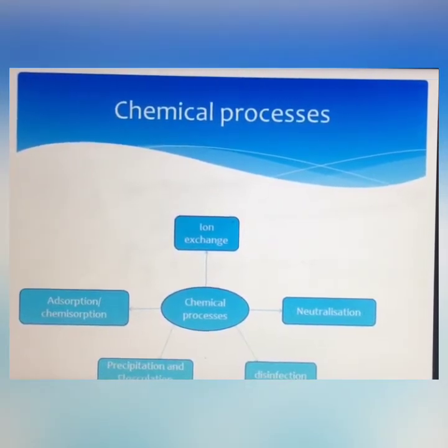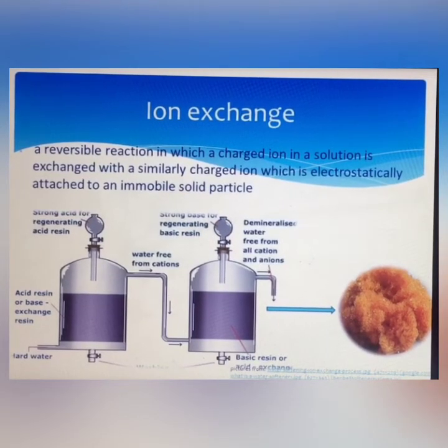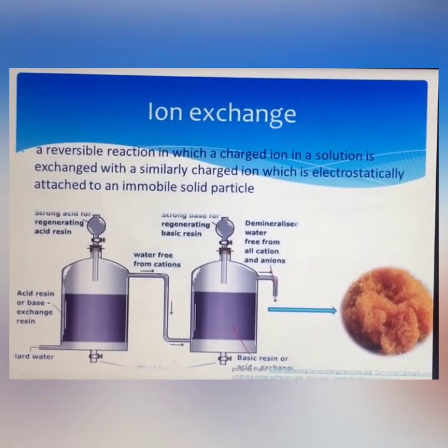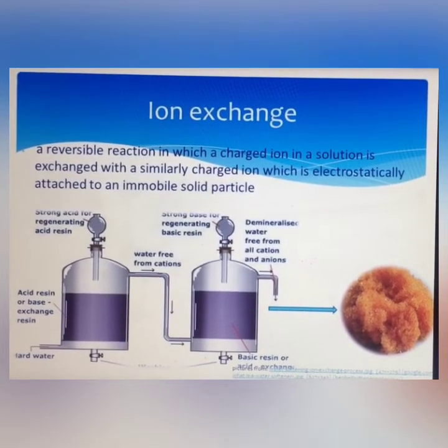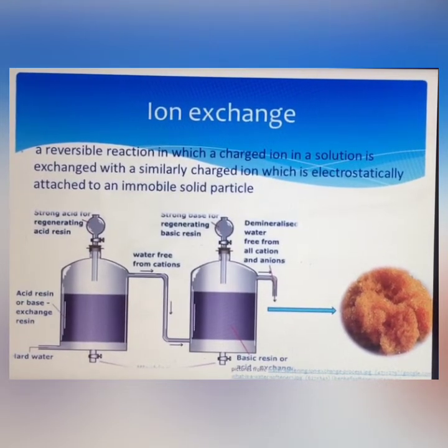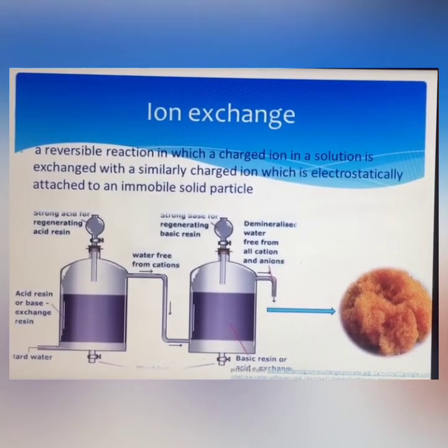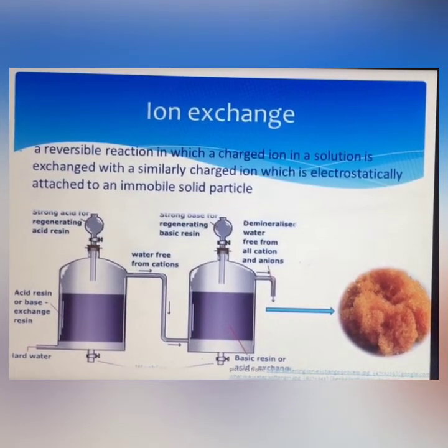These are the most important chemical processes used in wastewater treatment. Ion exchange. Ion exchange is a reversible reaction in which a charged ion, which is unwanted in the wastewater, is exchanged with a similarly charged ion, which is electrostatically attached to an immobile solid phase. The implementation of this method is for softening of the water. This method is suitable for removal of heavy metals and anions.